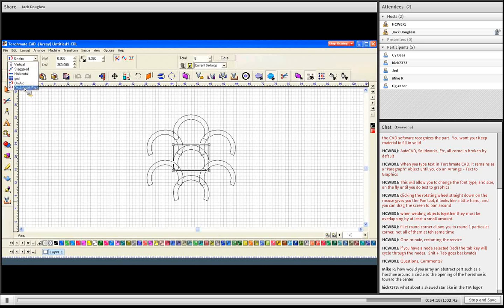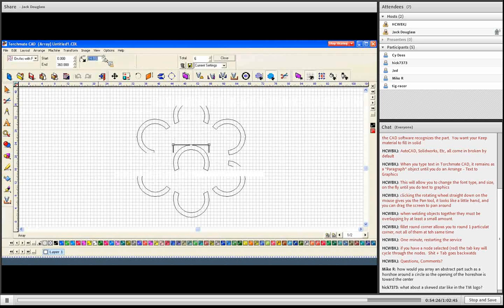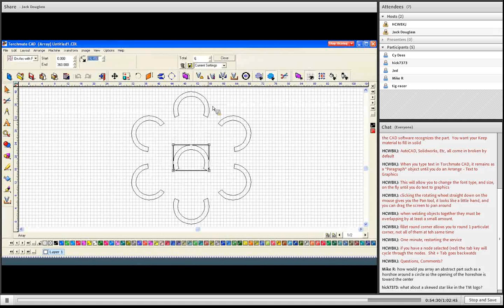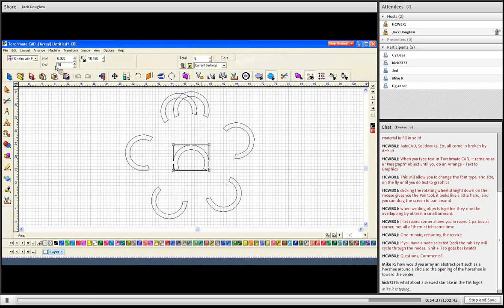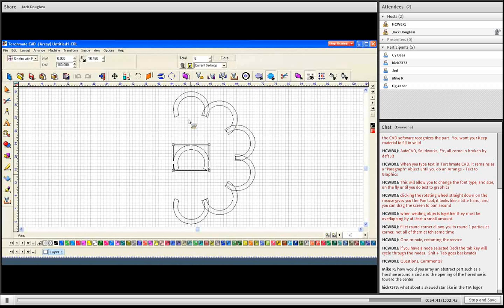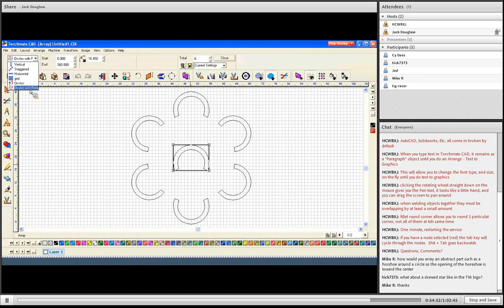There is another option in here, on arc with rotation, and what that does is basically what he's describing. It will rotate the parts equally around the space that you're looking for. So if it was a semicircle, keeping them all basically facing the center, the bottom facing the center. So it's fairly simple to do. Just use on arc with rotation, along with your starting degree 0, your ending 360, radius, and the total number of copies that you want. So not overly difficult to do. Just remember that there are 2 different arc arrays: an on arc without any rotation and one that rotates it equally.